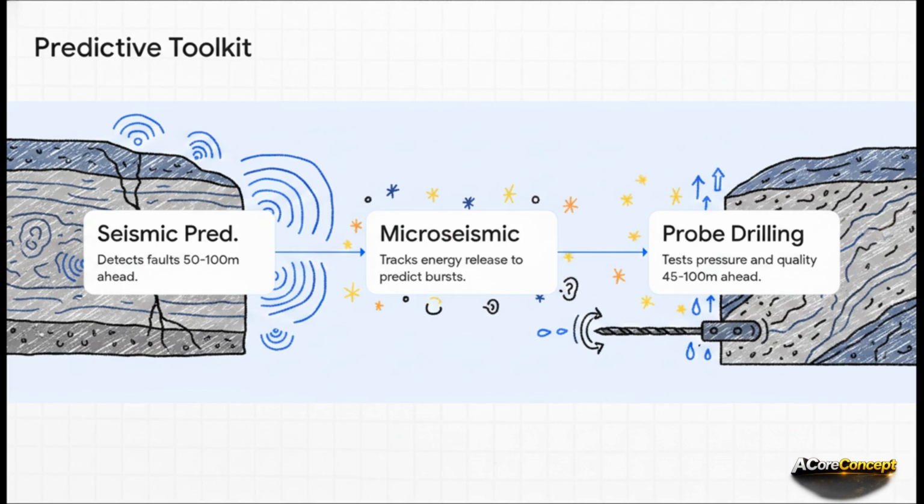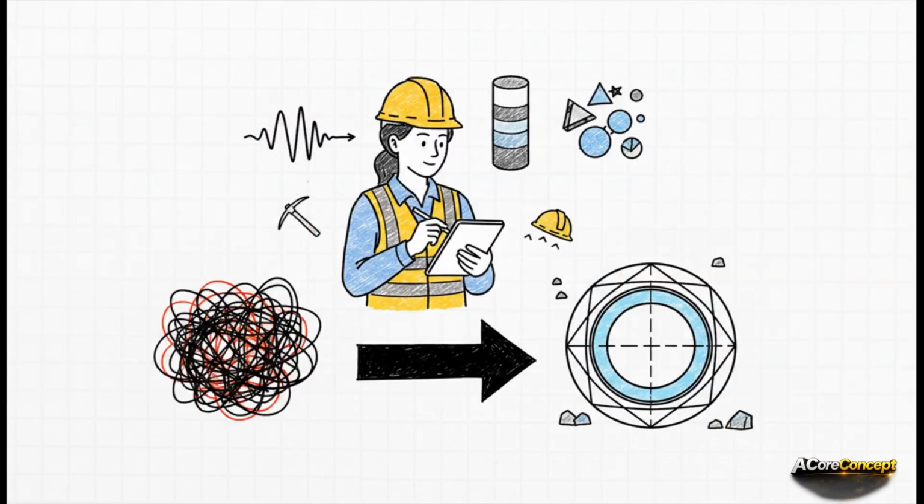This is where we physically drill long, small diameter holes ahead of the excavation to definitively test water pressure and verify the rock mass quality. All of this data underscores the absolutely indispensable role of the engineering geologist.